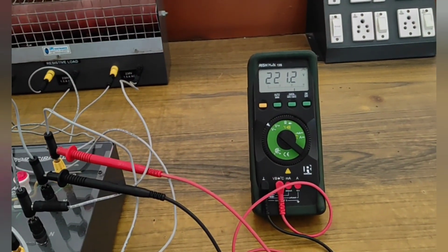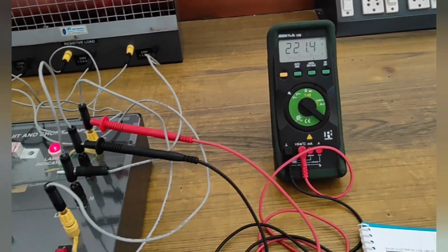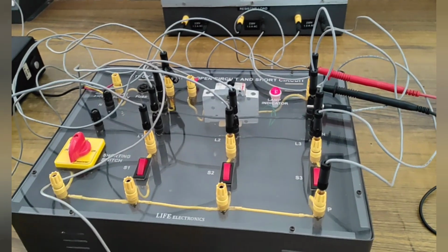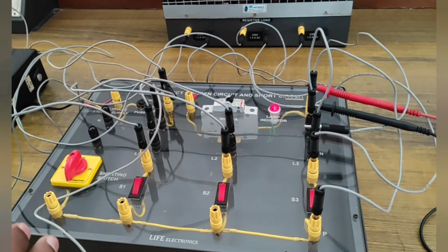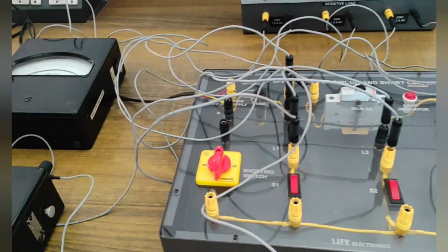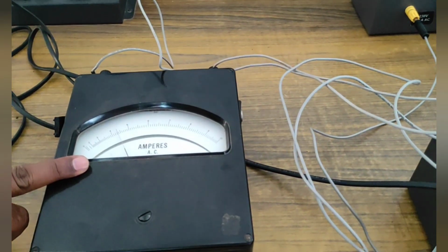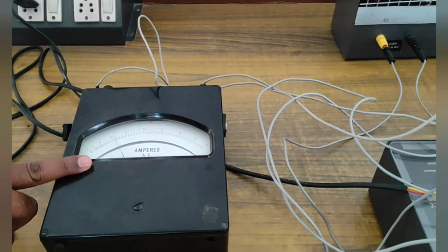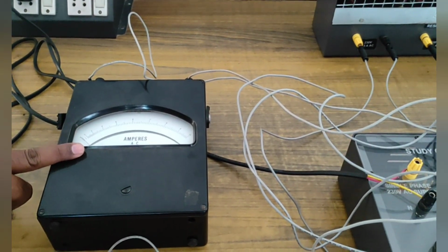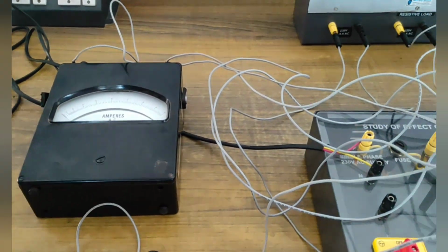Within some fraction of time it will short circuit because of the load. It reaches the maximum current. Whenever it reaches the maximum current, then it will trip. You can go through here, come here. Here you can see the current. Immediately it will be shut down. The current becomes 0. So this is called short circuit with load. So we need to note down that it is 4.5 amps.